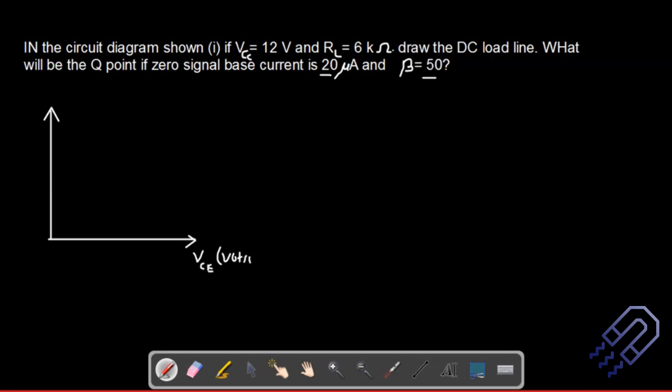Because that will basically remain the same. So it's actually easy on this part if VCE is already given, right? So you're getting 2 milliamps. So everyone should be getting 2 milliamps. Please check. Okay, and use the same equation, the Ohm's law, the KVL equation. Okay, and on this side you should be getting around 12 volt. Okay, so please check, all of you should get that.